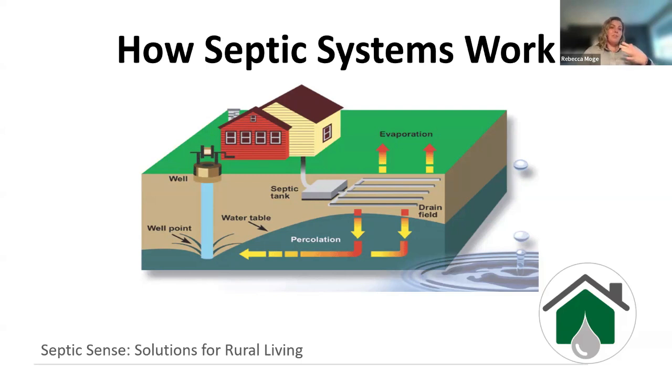So if the sewage we're putting in the ground isn't treated properly, and it doesn't have the right amount of soil to achieve that treatment, it can potentially contaminate underground aquifers, and now even your own well or your neighbor's well, or 10 miles down the road, someone else is drawing that back up to use in their house, and then ingesting and using that contaminated water source. So that's the sort of cycle that we're looking at.